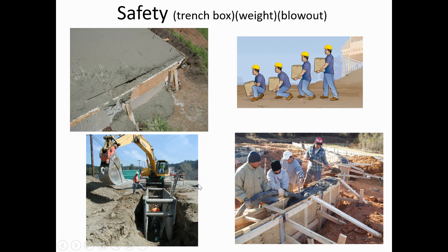And while we're talking about safety, a lot of times when you're doing concrete, it's below the ground, below grade. Anytime you're digging a hole, you can't get in a hole that is deeper than your waist. That's one of our safety rules in general, because if there's a cave-in, it would trap you down in the hole. What they've got here is obviously deeper, over this worker's head, so they put a trench box in. They dug the hole and put this big, huge metal reinforced box in there so that the worker can work safely down in the hole.